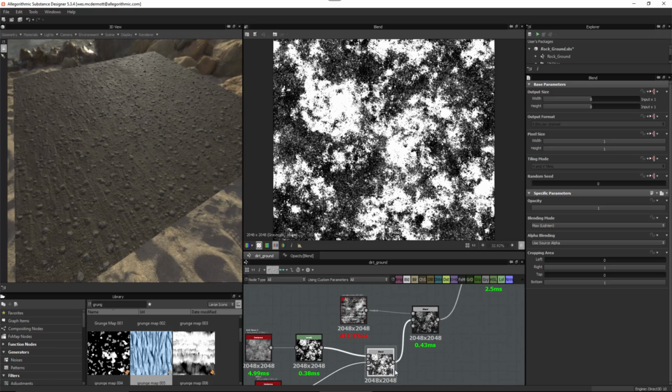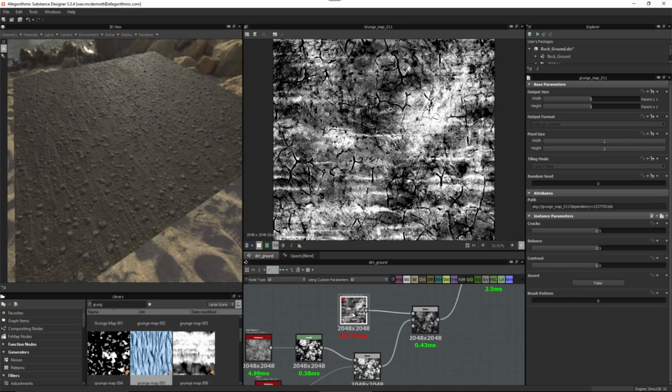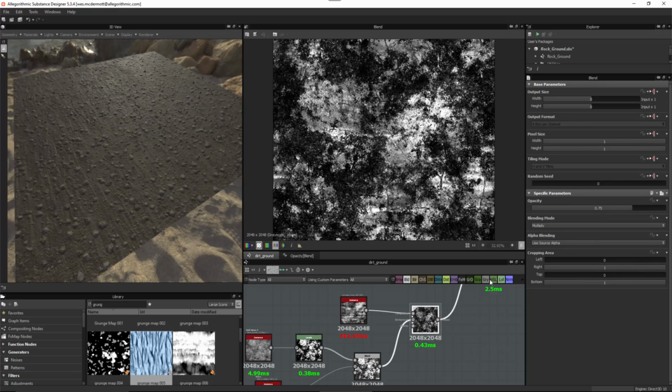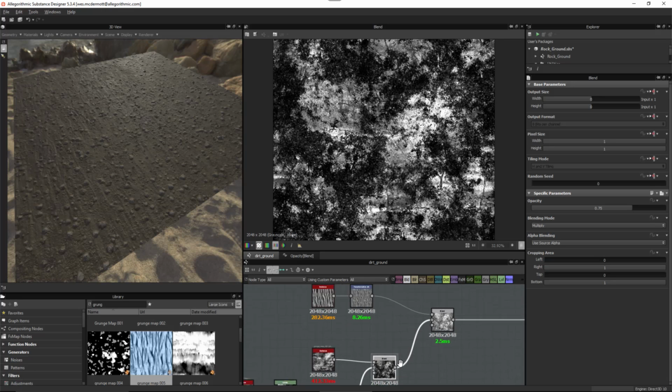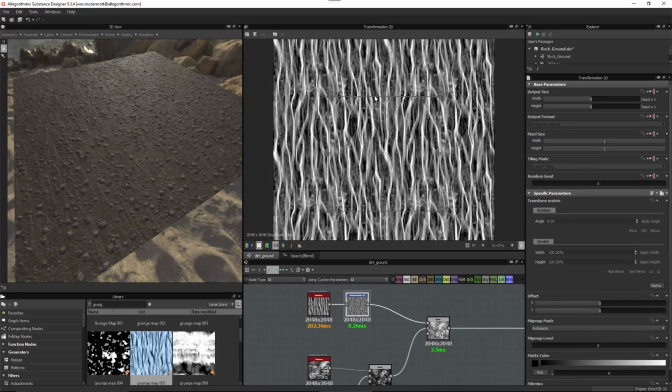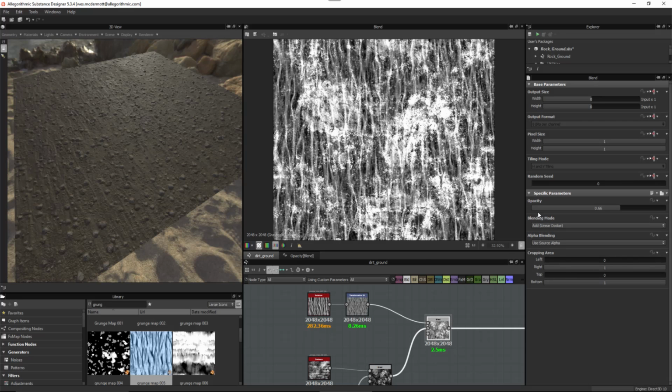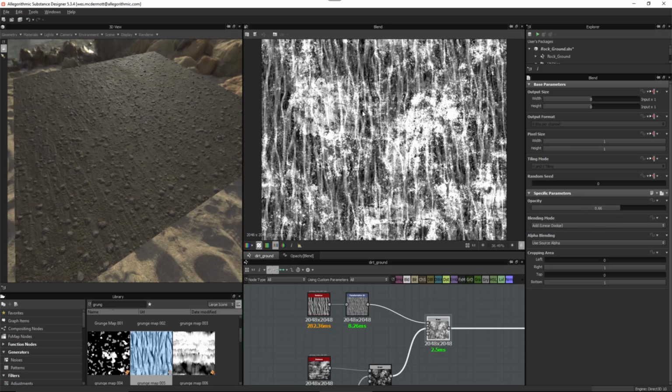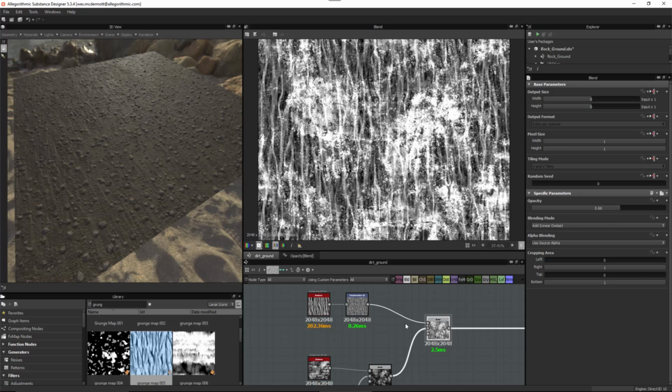And then finally, I'm going to combine this map with this map. If we take a look at our blend node here, you can see I'm using a multiply and I just drop the opacity here to get something like this. Once I have that, we can go back to the wavy line noise that we had here, and we're combining these with an add linear dodge and then just dropping the opacity down. So this ends up becoming the noise that I created.